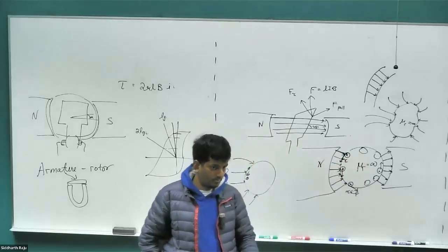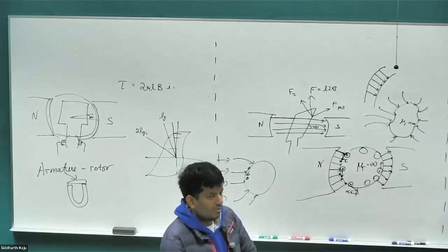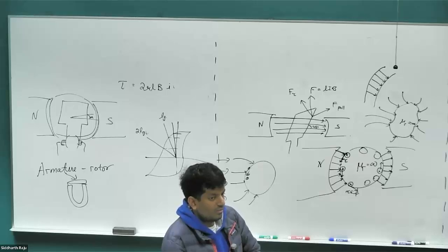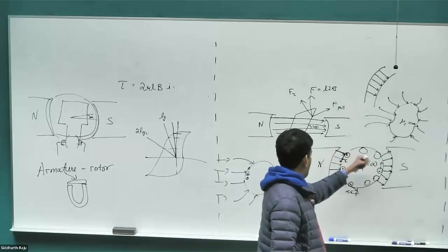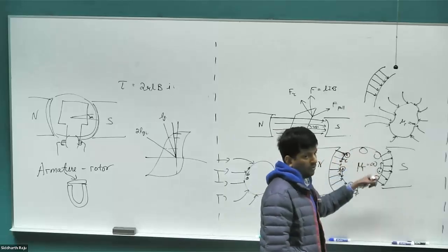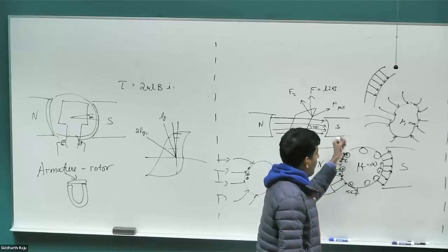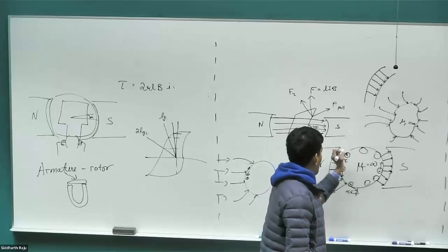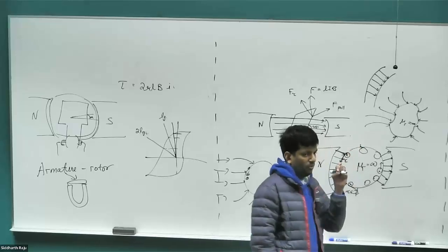Yep, Thomas. So if you only made it so it was two conductors, that would still hold true, right? I mean, until it reaches the bottom where there isn't really north or south. Yeah, no, at every single point, it doesn't matter how many conductors, you don't need a conductor at all. Let's just say remove all of these conductors. If you just had an iron sphere or iron cylinder, all these lines would terminate perpendicular. At the top part too, they would terminate perpendicular, but the magnitude would be very tiny.